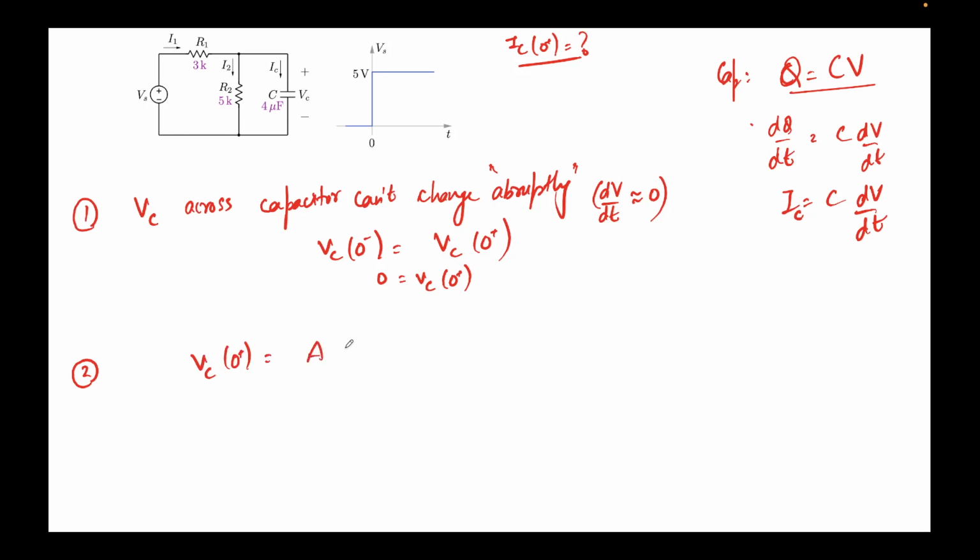This is the general form of the expression for V_C for these types of circuits, by which I mean circuits with only resistors and maybe a voltage source. Now we'll try to find just the values of A and B. And by the way, tau is the time constant that we already know, so we need not worry about that.